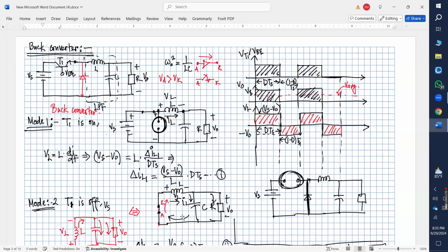When this transistor is operating, or short circuited, then the entire Vs will appear across the diode, making this diode operate in reverse bias, right? So the maximum reverse bias voltage that the diode should handle should also be the source voltage, right?